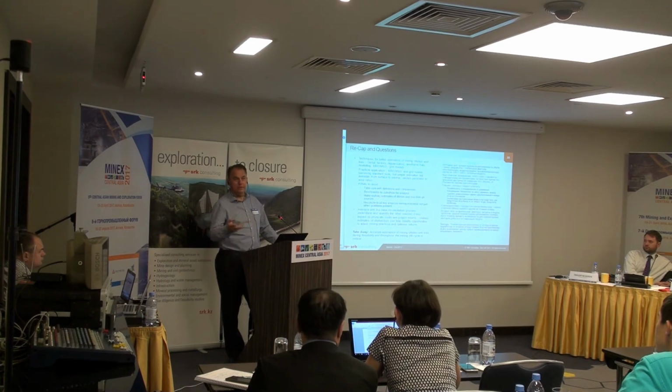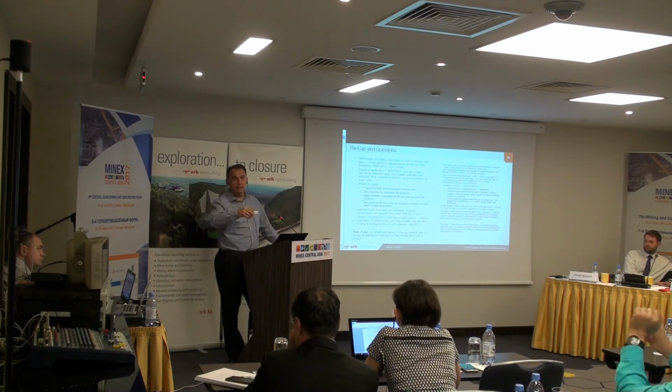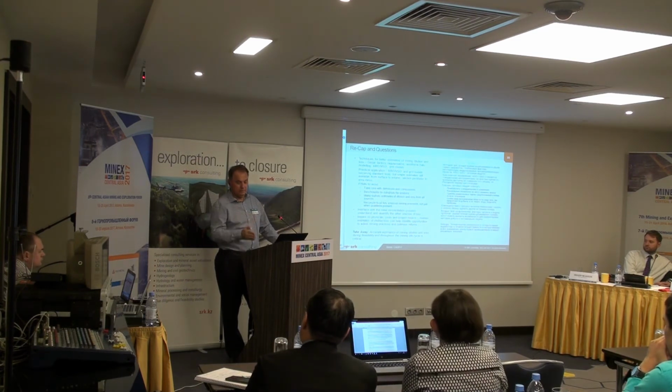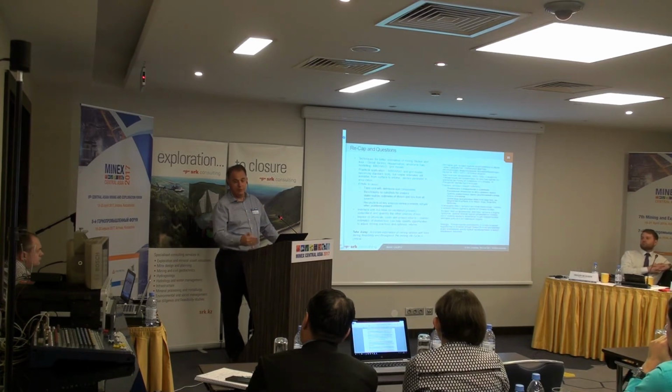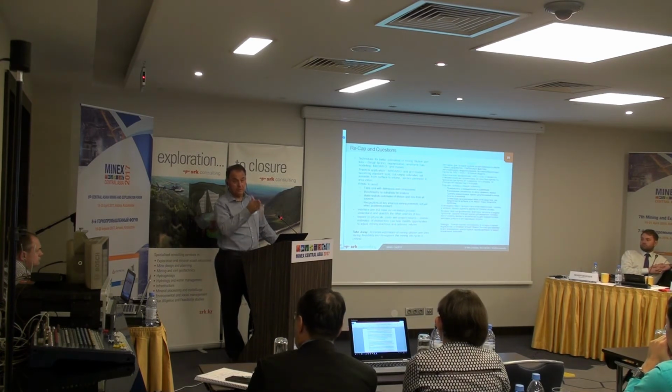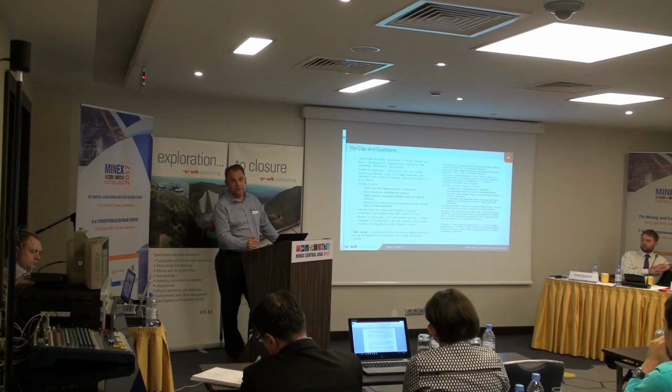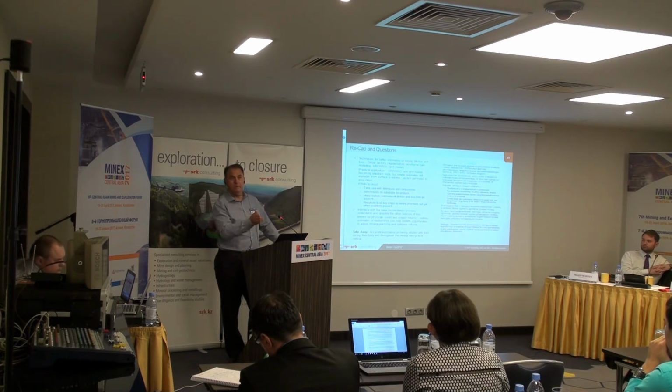Following the shot, the surveyor would pick it up, and that would be used. You'd have 2 or 3 of those in a shot. That would be used to provide an indication of movement along strike, the ore body. The direction of the blast was always orientated along the strike of the ore body, and the predominant movement of the shot is therefore always on the strike. With modern electronic detonator systems, you can control exactly what angle the blast moves at.